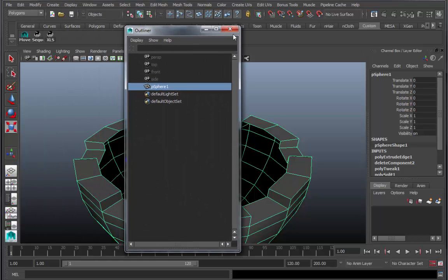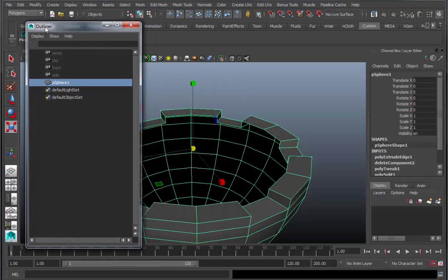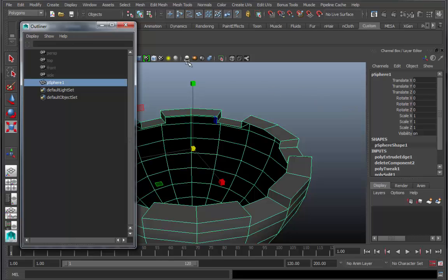So now that we're here, let's go into the outliner here. If you want to have your outliner on the left or on the right, wherever you put it, or you use the channel box and layer editor, we're going to rename this so that we know exactly. We start being very diligent about renaming these meshes. So in this case, it's going to be Pball_bottom_mesh. You can't use periods. You can't use spaces with Maya for naming things. You've got to use underscores. Very Unix. So we've just named it Pball_bottom_mesh.